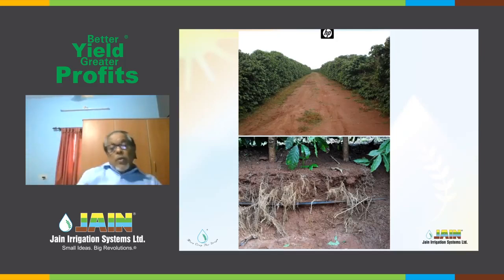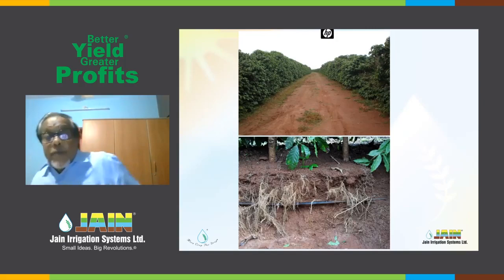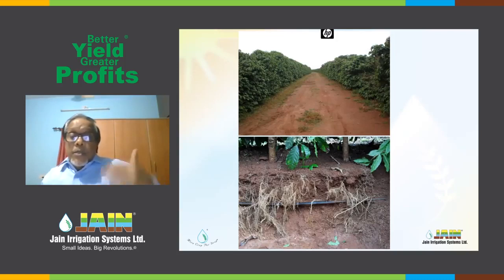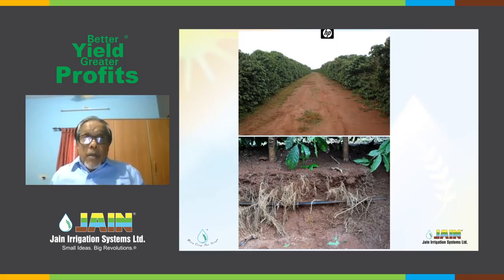and it's a totally different management of coffee. So in coffee we also do subsurface drip irrigation. So the placement, you can see the depth, how much it is. It cannot be too deep there. When it is too deep, the heaviness of the soil can collapse the drip line also. So there is an optimization of the depth and the placement based on the soil texture. Again, the dripper to dripper spacing, emissions, everything is decided.